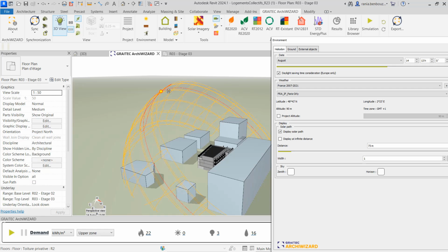That means that the solar gain will mostly be absorbed through the roof and the east facade in the morning, but also the south facade around noon and a part of the afternoon when the irradiation levels are high. Since the position of the sun is high in the sky, the sun rays will hit the southern glazed area with an incident angle.